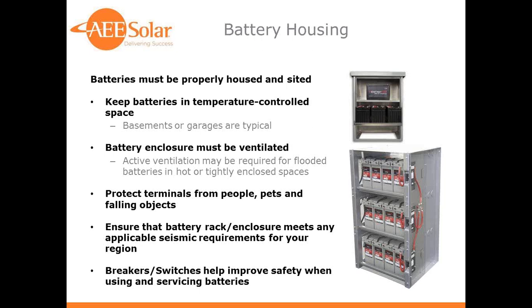Obviously, batteries need to be kept away from people, pets, and falling objects, and from people that aren't actually servicing the batteries or authorized to work with them. You don't want to have kids and pets and metal objects falling on your batteries, so make sure they're well protected. If you're doing a stacking system with batteries, make sure that it meets any applicable seismic requirements for your region. A lot of the pre-made battery enclosures and some of the industrial grade batteries have earthquake rated racking, so that may be important to you depending on where you're located.